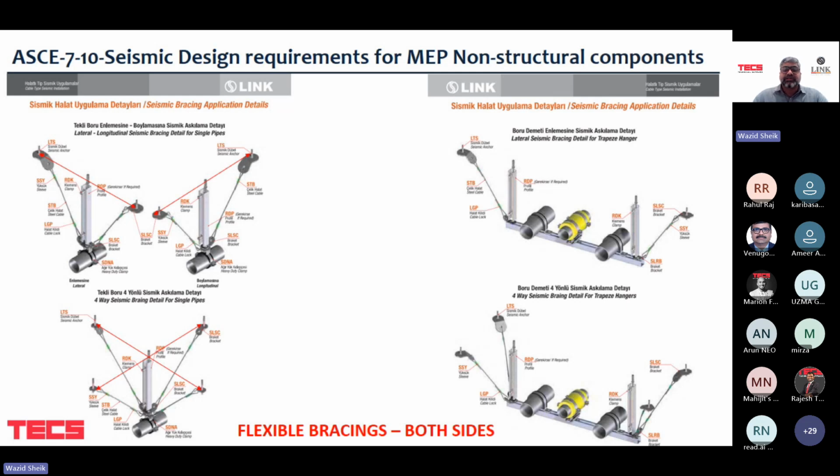And this is a crucial engineering principle, because the braces themselves should be connected with flexible fittings. You see here, nothing is rigid. The reason is, if the braces were rigid, they would snap immediately. So the flexibility allows the brace to accommodate the structural movement without breaking, while maintaining its restraint on the pipe. So in summary, we select the bracing detail from a simple lateral to fully forward, depending on the pipe's importance and the seismic demands, which you always implement with flexibility in mind.